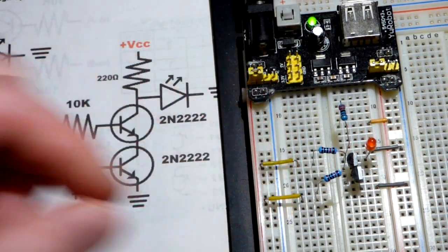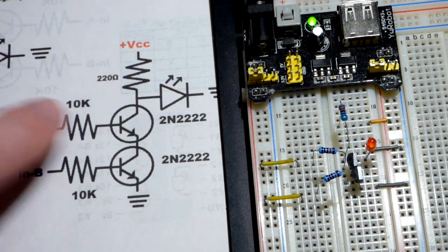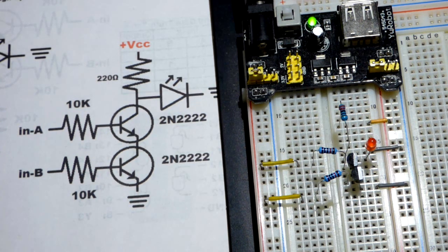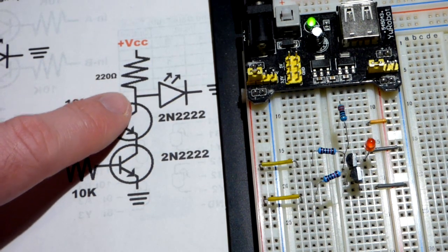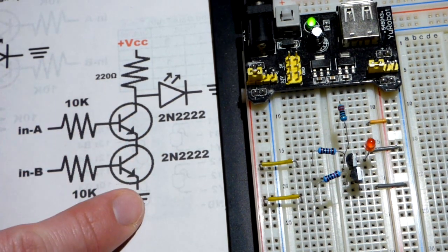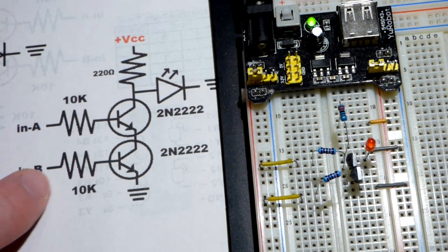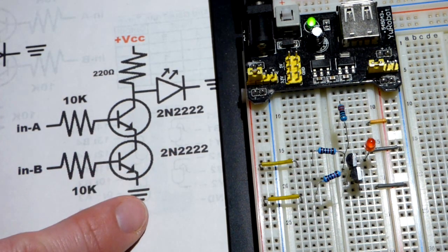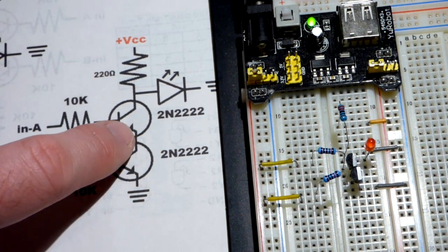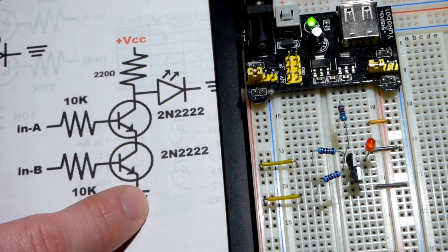Now you can see that it is off, so we gave both transistors a positive signal, and the LED, our output in this case, is off, and that's because, just like with the switches, we have a direct path to ground. So there's a little bit of current going through the base to emitter here, but it's enough to get the transistor to fully conduct.